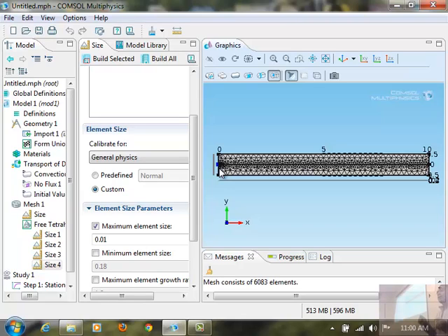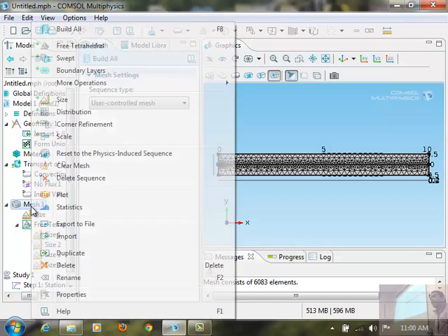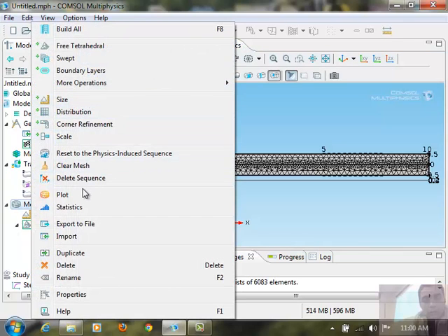So now once you have generated this top source mesh, you can just sweep it and it will be propagated in the z direction, with all these refinements, local edge refinements, local point refinements. So you can just right click and select sweep. Okay.